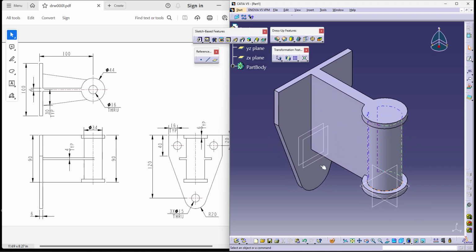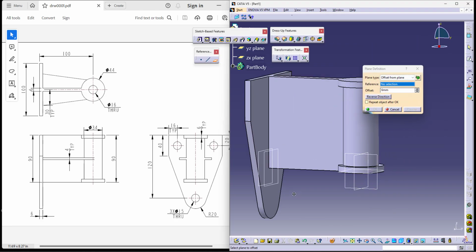This is how you'll be working on a simple model wherein you have a combination of plates and selection of your origin. Now the remaining are very easy parts. So the first thing is I need to take these ribs. As you can see, they are called supports or stiffeners. They are located exactly at the center. So let me take a plane at the center since I have not maintained symmetry in the beginning.